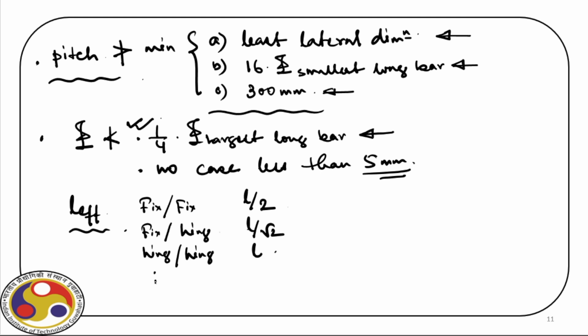And there are other conditions also, but in IS 456, there is a dedicated table that modifies this value slightly, and then it gives basically the L effective for different boundary conditions. Nevertheless, the point to be noted here is that the L effective depends on the boundary condition.